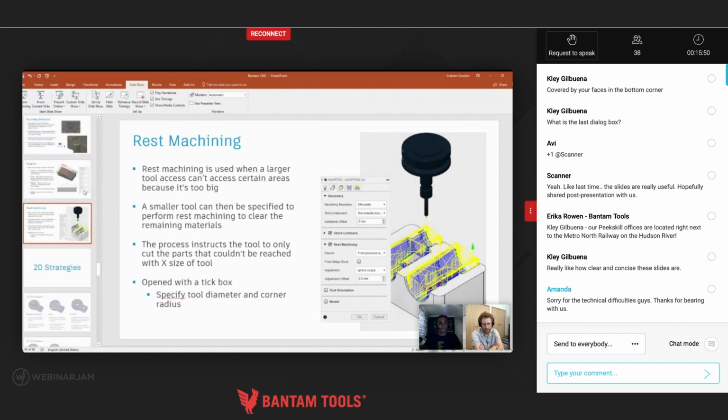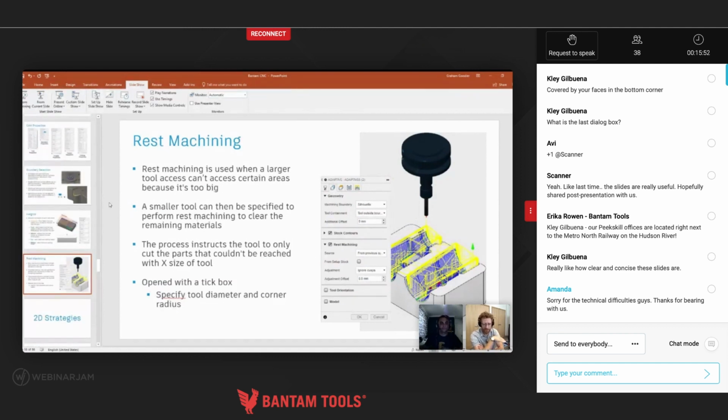And Graham, just so we can weigh in there, most of those things are set by default, but like in facing, it's usually set from the top of the stock to the top of your model, and you would have to adjust away from that. You're not always adjusting all of the numbers in the heights tab. Yeah, that's what I was trying to say on the CAM properties page. Sometimes it looks like you have to do everything here, there, and there, but trust me, you don't. And like you say, the top height default is always the top of the stock for safety reasons. I'll get more into that in the demo.